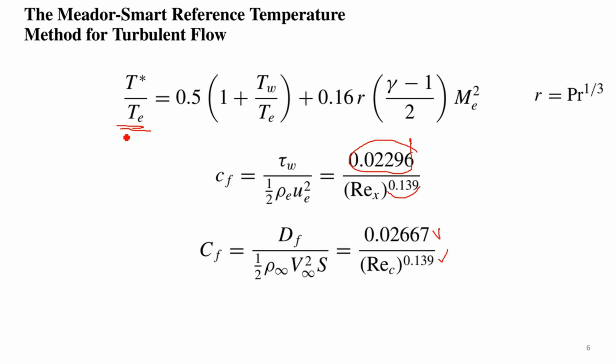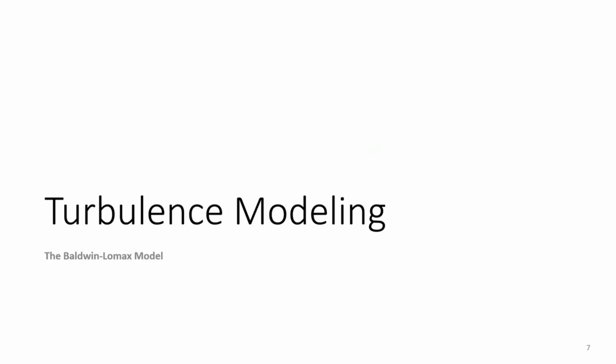Very useful. The modeling of turbulence is done with various different models, of different scale. There are so-called zero-dimensional models, which do not involve any differential equations inside the model of turbulence. There are one equation models, like Spalart-Allmaras, for example.